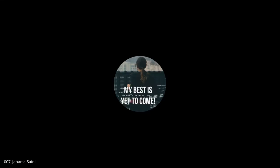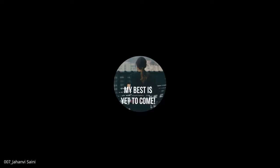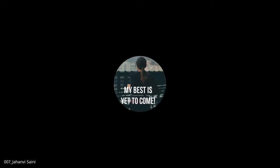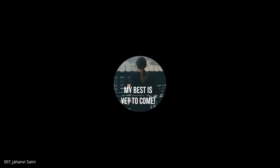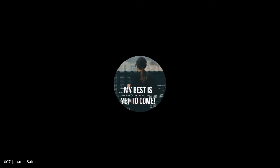Sir, Jahangir Saini. Tell me what's e to the power At known as? Sir, it is state transition matrix. State transition matrix. How many methods have I shown you to compute the state transition matrix? Three methods. So which method are you more confident with? Laplace and Cayley-Hamilton method. Okay. What do we do in Cayley-Hamilton method? So first of all, we'll assume this e to the power At equal to f(A), and we will form its corresponding scalar.